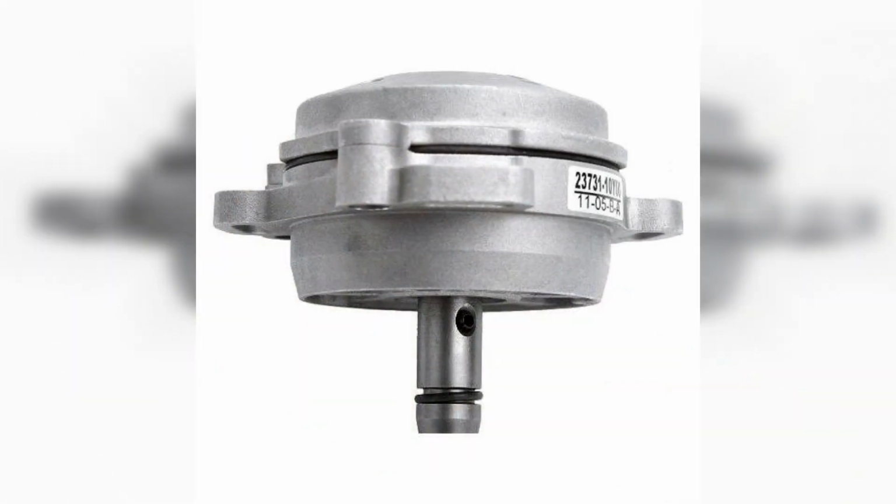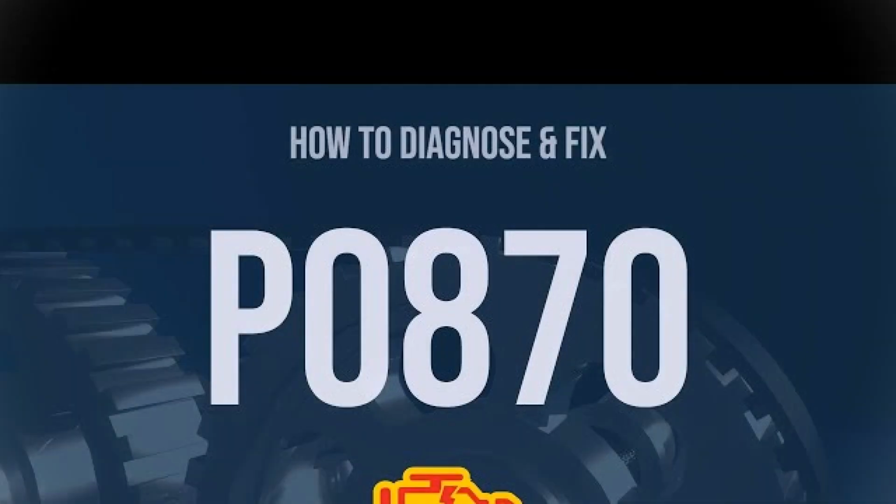What are the symptoms of code P0870? Code P0870 triggers the code and also the service engine light. Most mechanics or technicians also say that a major sign that this code will appear is the smell of overheating transmission fluid and smoke that may appear. Drivers will experience transmissions that don't engage or are impossible to start and operate.